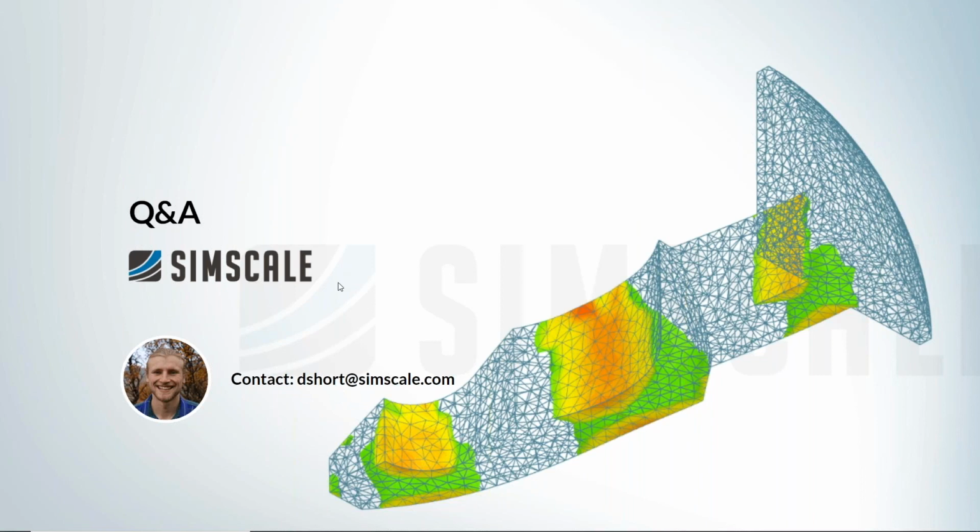So I recommend always, when possible, use second order. It's going to be more efficient and more accurate. But there are cases where we actually want to use first order to streamline convergence and things like this. But there we have to just be mindful of the fact that we're going to be approximating curvature rather than really having it explicitly in the shape functions.